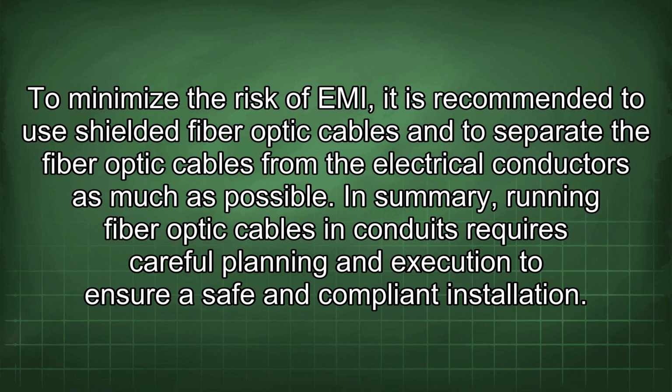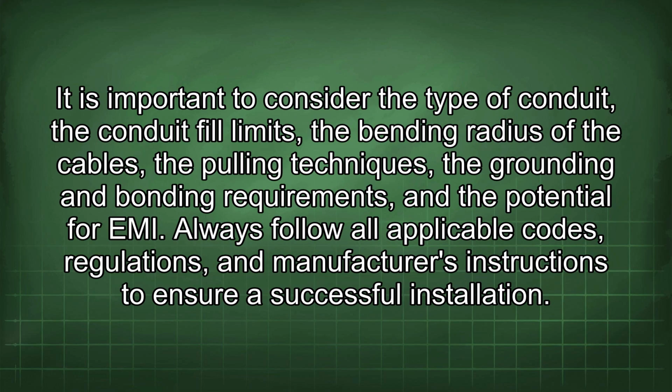In summary, running fiber optic cables and conduits requires careful planning and execution to ensure a safe and compliant installation. It is important to consider the type of conduit, the conduit fill limits, the bending radius of the cables, the pulling techniques, the grounding and bonding requirements, and the potential for EMI. Always follow all applicable codes, regulations, and manufacturer's instructions to ensure a successful installation.